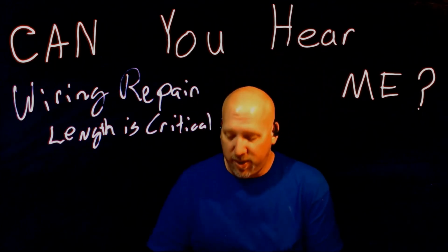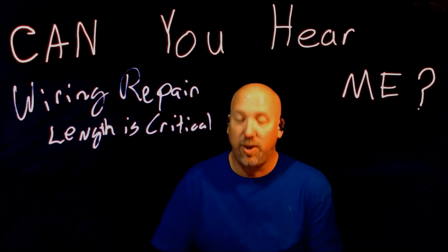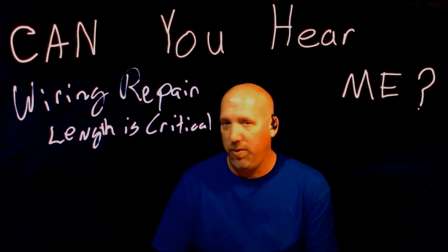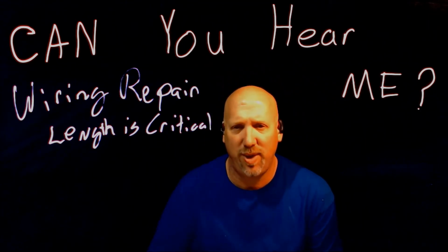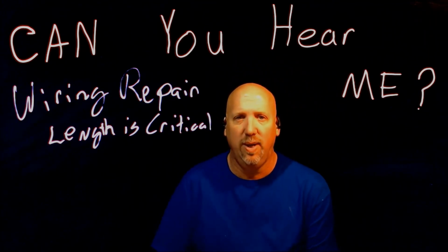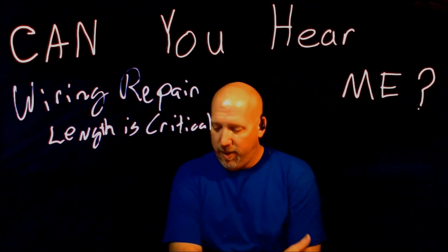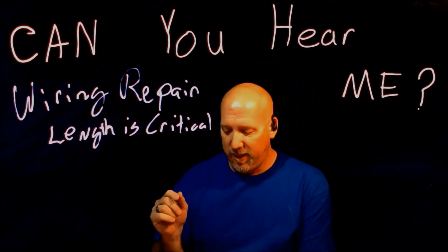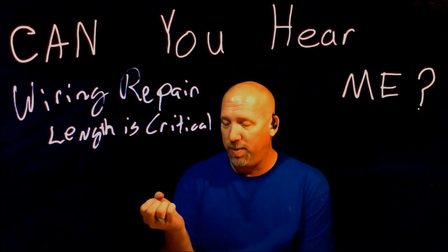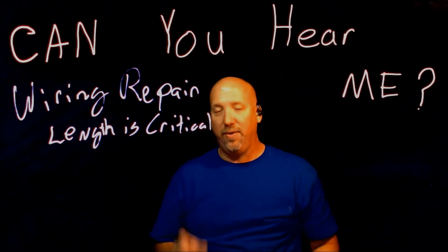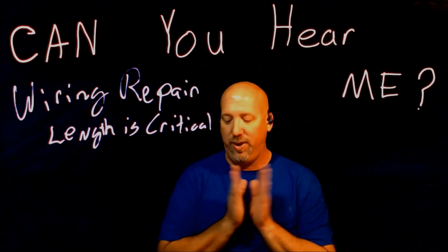When soldering connections or splices in network wires, use a rosin core mildly activated solder. Never use acid core solder. You know this. Don't use acid core solder for automotive work. Acid core is for other things. Use a rosin core solder. And also always use a heat shrink over the wiring. Always use a heat shrink over the wiring repair with at least a 1/2 inch overlap onto the insulation to the side of the wiring.